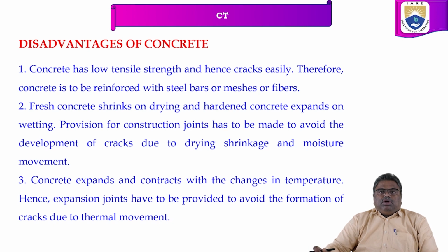For example, whenever we are building a very lengthy concrete wall, in between we have to provide the expansion joints due to drying shrinkage and moisture movement, at particular intervals.